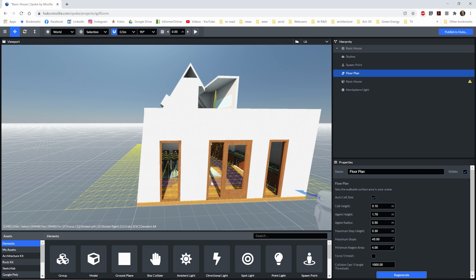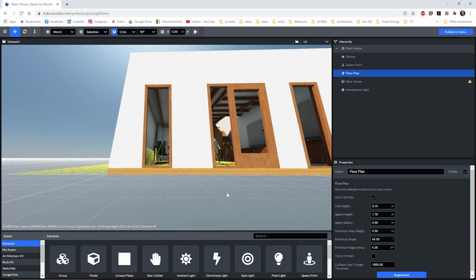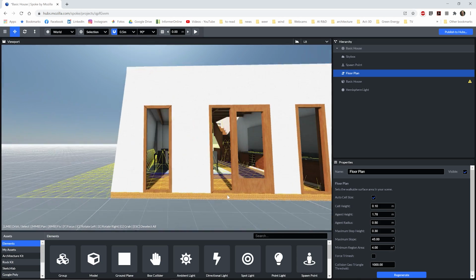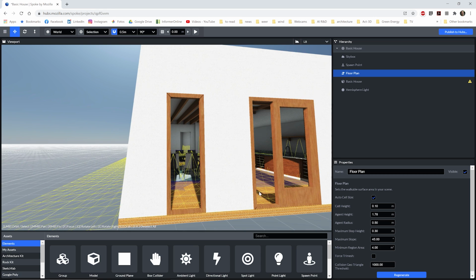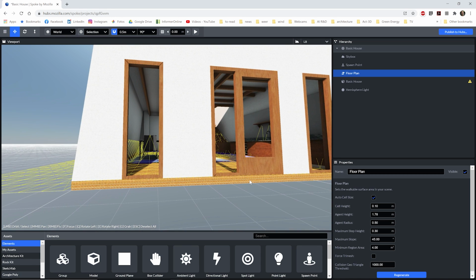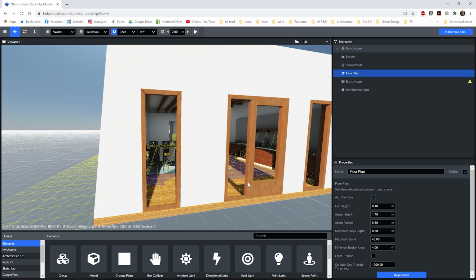Upon closer inspection, we can see a blue transparent plane floating above the yellow lines on the floor, which seems to correspond with the floor level of the real-life room that you experience when walking in it with a VR headset. There's no way to lower this plane, but we can get around this problem if we generate the floor plan's collision mesh with an invisible copy of the house shifted 40 centimeters lower, in combination with a visible copy of the house that will have the options walkable and collidable turned off.